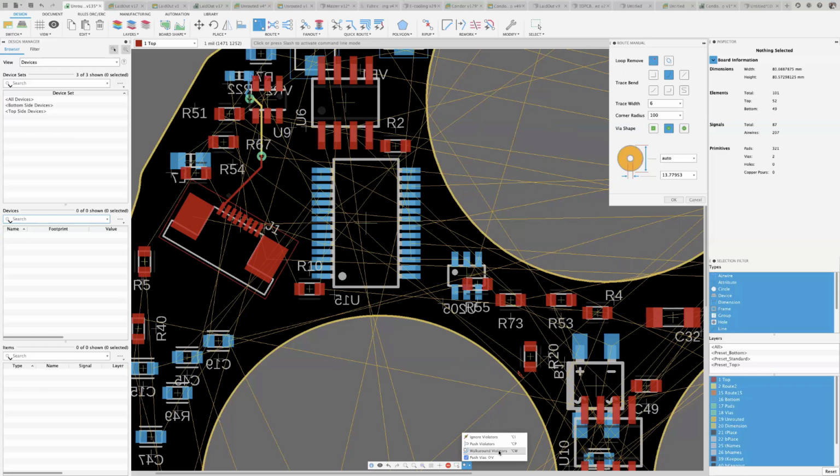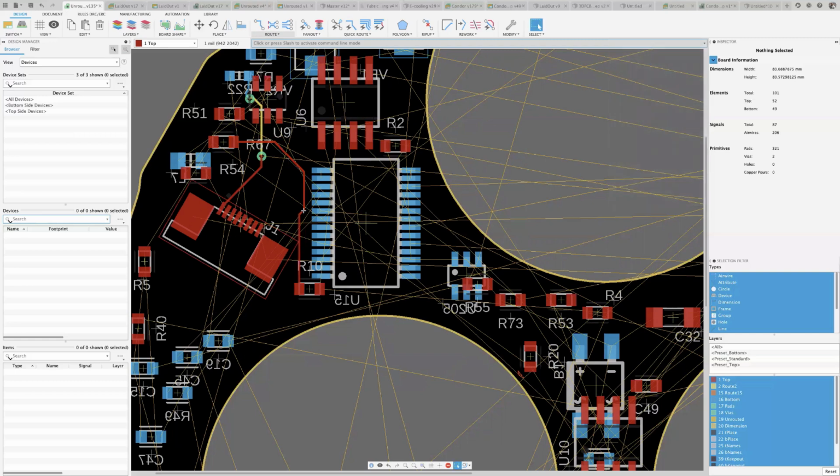I think this is a really good choice to use because it contours anything that is on your board already, and it will avoid any errors. So let's say, for example, I start routing here, this line here. As you can see, it's going around and it won't violate anything unless I actually allow it to. So I could just go ahead and do my routing here and go around here, and complete my routing. And I could actually stop here if it's a straight shot. I could hit enter and Fusion 360 will actually invoke quick route and finish the route for me, as you could see.